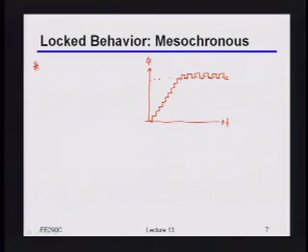Yeah, there we go. So the first thing you care about is just the worst case step size. Because if I have some DAC-looking thing, which is that phase interpolator, which is just translating digital codes into phases, and I know I'm always going to be jumping back and forth, then what I care about is the biggest jump that I could possibly be taking. Because that sets the magnitude of the dither that I'm going to be getting in my system. It's absolutely true.